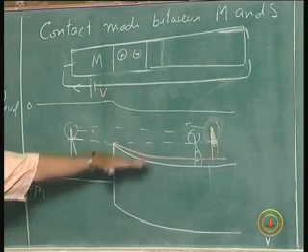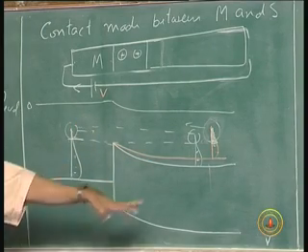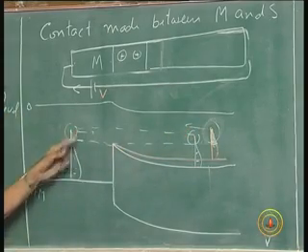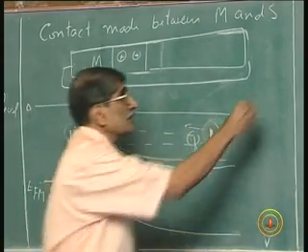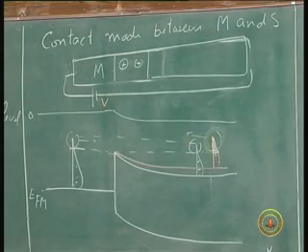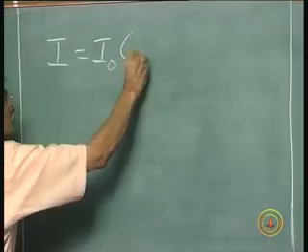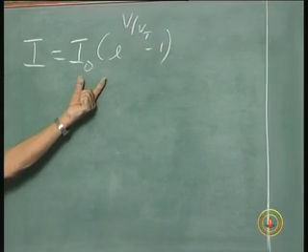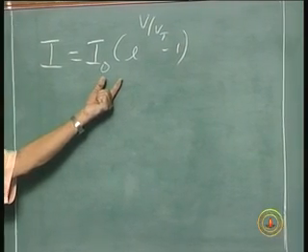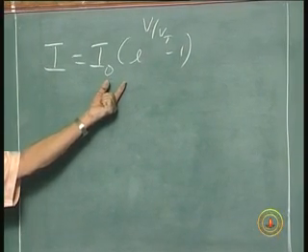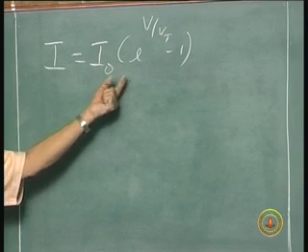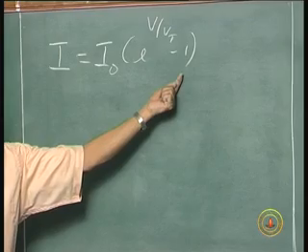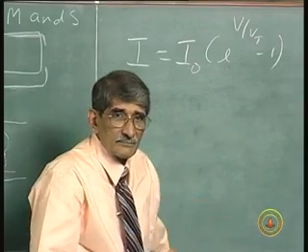So, why those energy band diagrams move up and down, and also these extra electrons which are present giving rise to current in that direction. Ultimately you have the current I equal to I naught into e to the power of V by V t minus 1, that is due to electrons. The first term is due to the electrons from the semiconductor to the metal, and the second term, with the minus sign, is due to the electrons from the metal to the semiconductor.